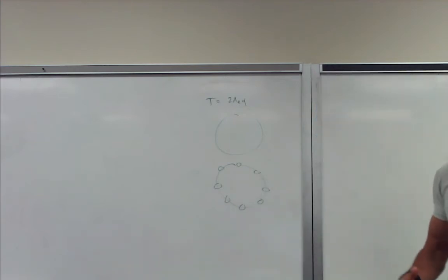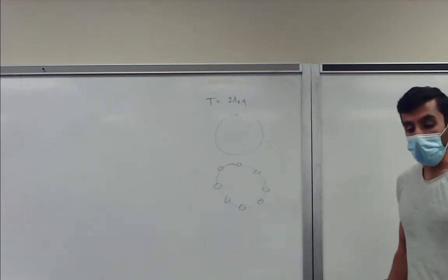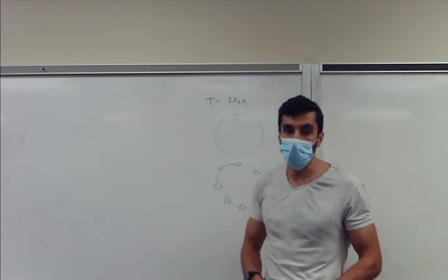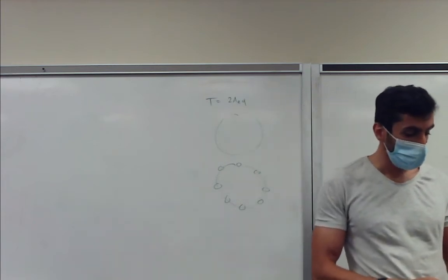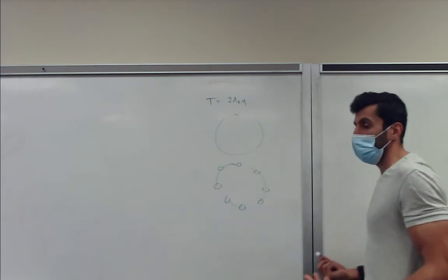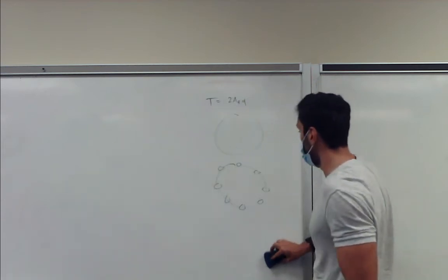So in that case, basically boom areas do not affect anything in calculating the shear flow, because it's just multiplied by 2 times the enclosed area. Okay. So that one is very simple. So just do it as is.